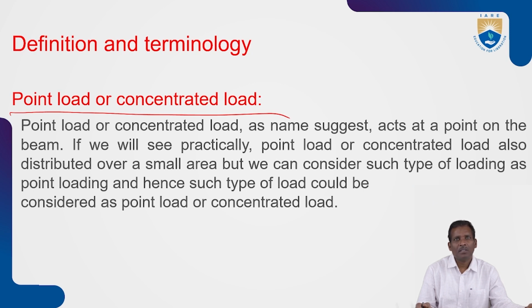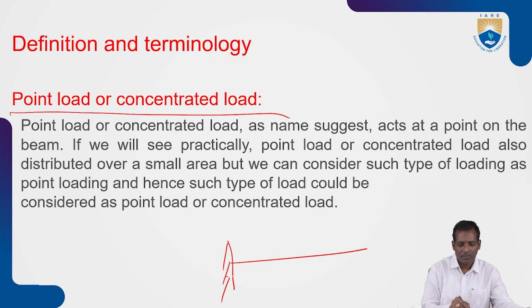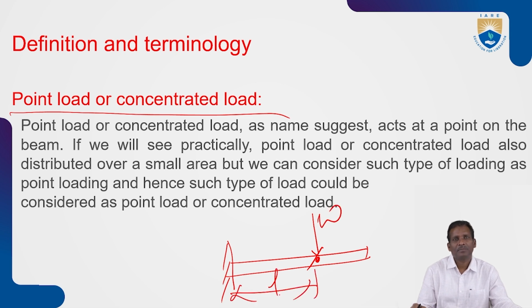The point load or concentrated load, as the name suggests, acts at a point on the beam. Suppose take a cantilever beam. At this point the load is acting, at a distance L. Practically, a point load or concentrated load is also distributed over a small area, but we can consider such loading as point loading, concentrated at this area only. So it occupies some area here.